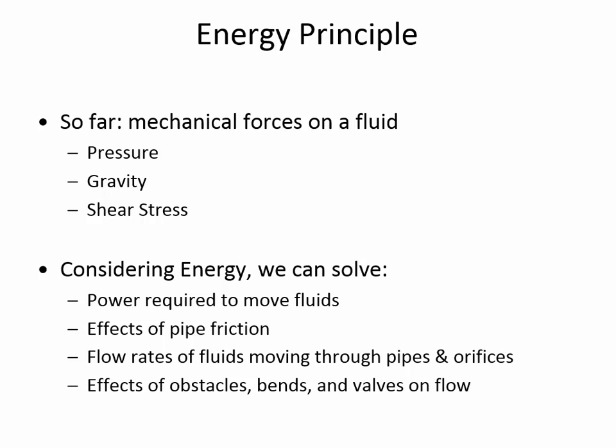And when there is a physical scenario that is governed by gravity flow, for example, a tank connected to another tank, but the water level is lower, and here's a pipe connecting the two, without the energy equation, you wouldn't know how quickly the water is transferred from the big tank to the lower tank. But when we start to look at how much friction is there in that conduit, then you can do the calculation of how quickly the water is transferring from one place to another.